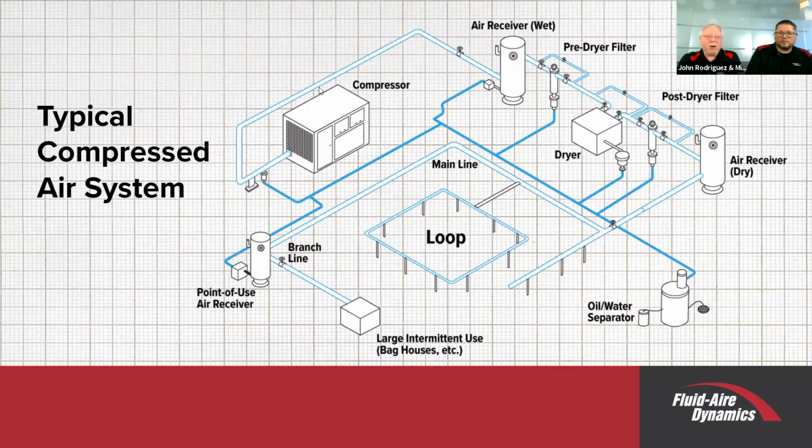Then it goes on, and typically the best situation is to have two tanks, a wet tank and a dry tank. The wet tank is another trap for moisture. Not only that, but the compressed air inside of it has a chance to cool down further. A couple of reasons you do that: if there's any problem with the drain prior to it, or simply to cool down the air a little bit further so the dryer doesn't have as big a burden.